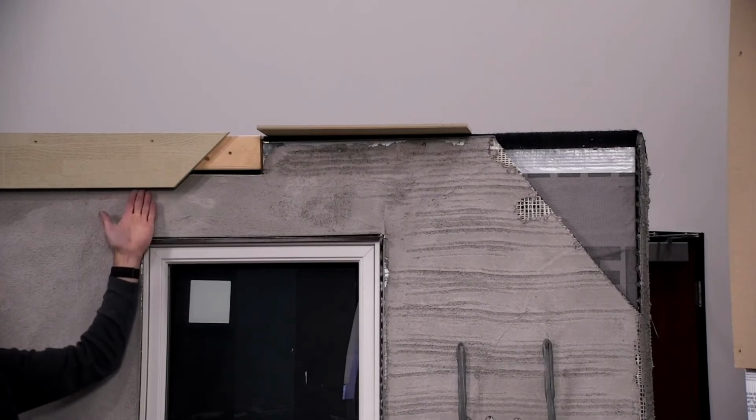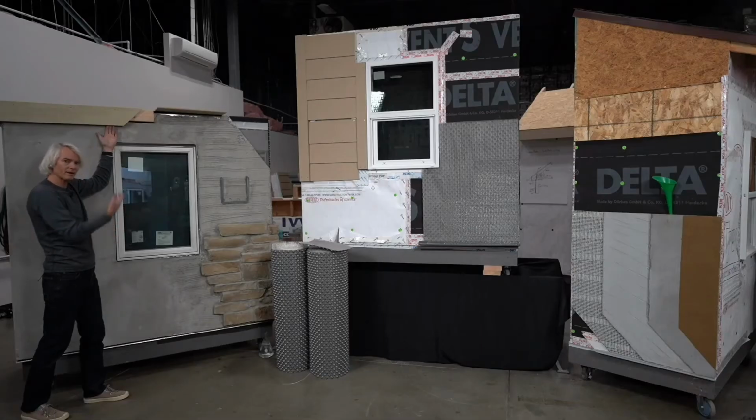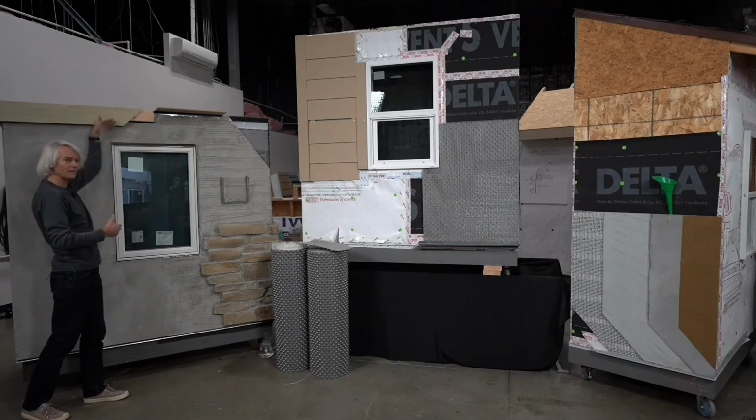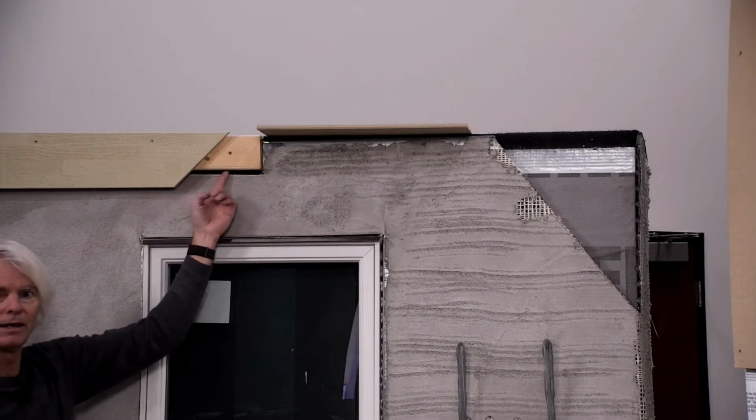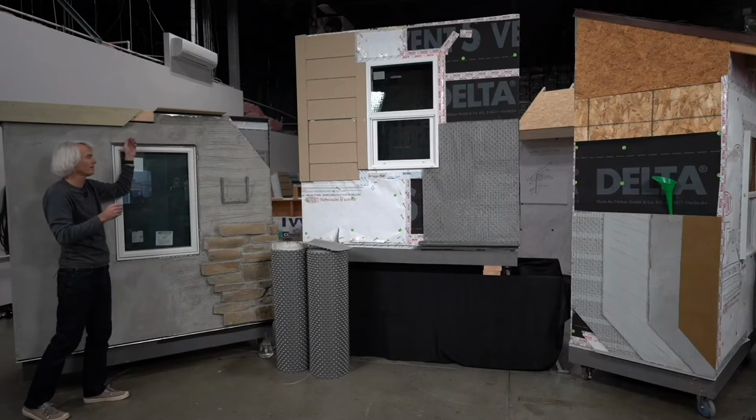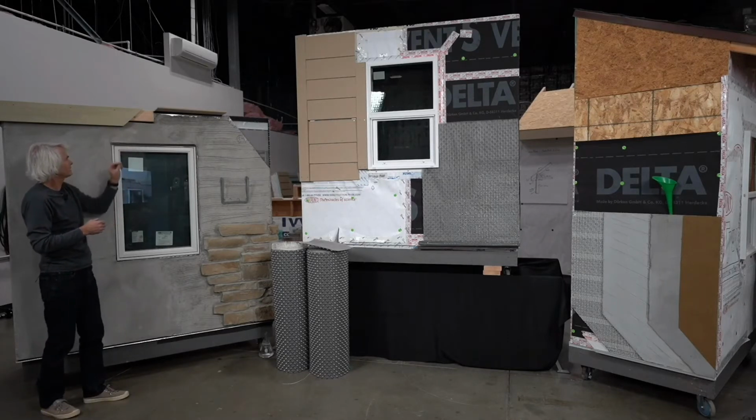The point is if we've got convective airflow or wind flow of air, we're able to allow air to basically escape out of this joint through this gap right here that we've created, and then our vent port right here. So it's concealed and you don't see it from the ground, and it's quite a clever way that we've seen in their installation guide to pull that off.